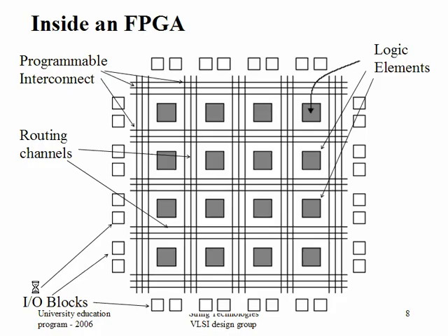This is what we saw yesterday. Correct? You will have what are called programmable interconnects. These are the interconnects, and the main things which hold the logic are called logic elements. Then other important blocks are IO blocks. Basically, these IO blocks have a lot of control in them. You can even program how much current drive should come from that pin. Also, you can configure one pin as an input pin or output pin. You can configure the pin to give either TTL voltage levels or CMOS levels. A lot of things are possible.